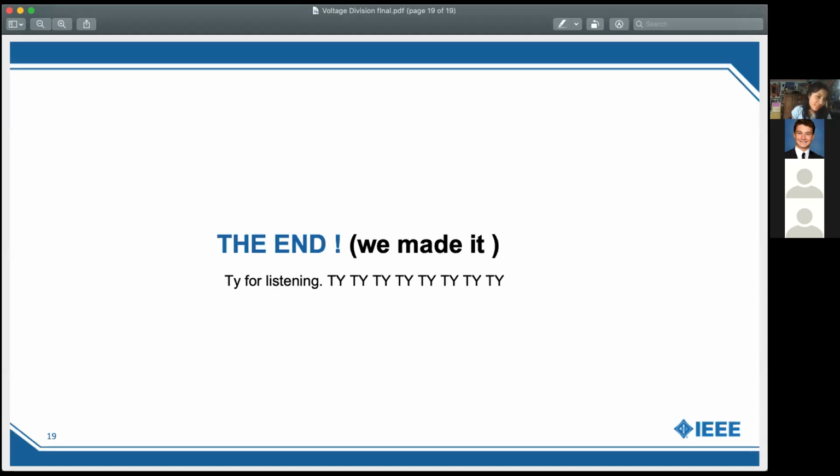How applicable is this stuff? Like you showed a circuit where there were like 10 parallel resistors. Would that ever be something that you actually find? Yeah, especially I see it a lot in the industry where you don't have the right resistor that you need. And so if you put a bunch of resistors in parallel to each other and make it the exact resistance that you need, then that's where you would use current divider, because you would be looking at that R equivalent value.